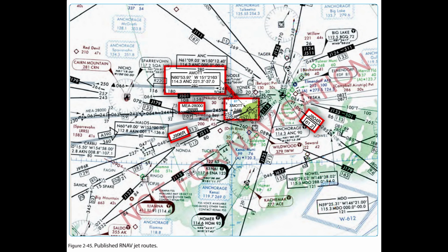Composition of designators. The prefix letters that pertain specifically to RNAV designations are included in the following list. 1. The basic designator consists of 1 letter of the alphabet followed by a number from 1 to 999. The letters may be A, B, G, R for routes that form part of the regional networks of ATS route